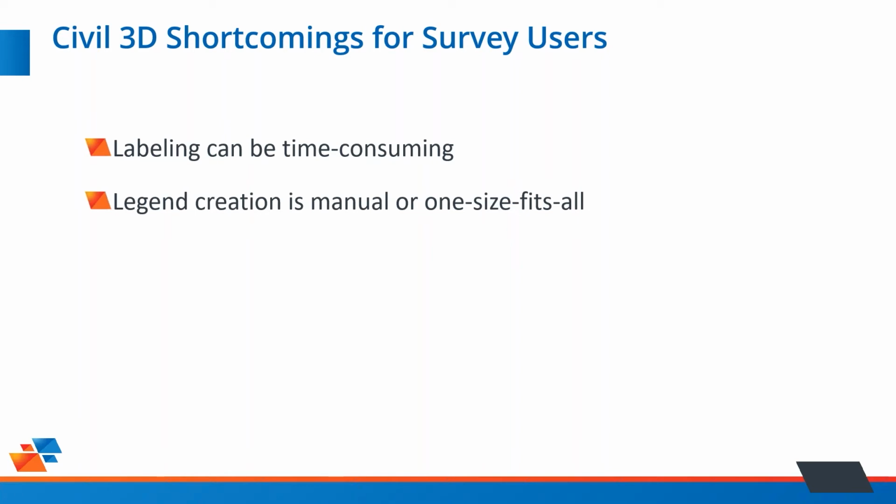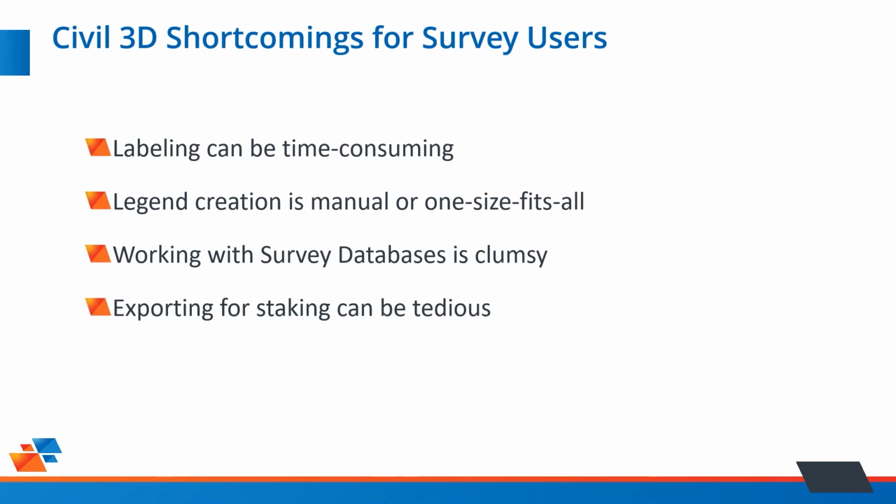Legend creation, perhaps an existing conditions topo. This is a very manual process. This, in fact, isn't unique to surveyors, but it's something we need to do, and we end up doing a one-size-fits-all or manual process. Survey databases, that's for processing topo data in Civil 3D, generating your automatic line work. Many of you perhaps aren't even using these because they're so tricky to use and clumsy. It's another big challenge in Civil 3D.